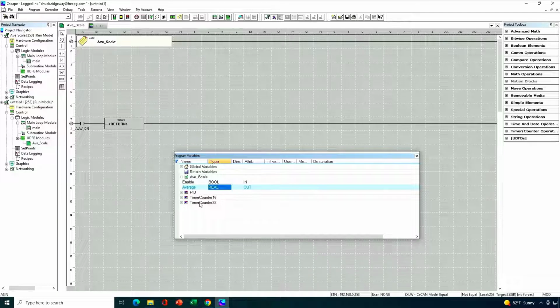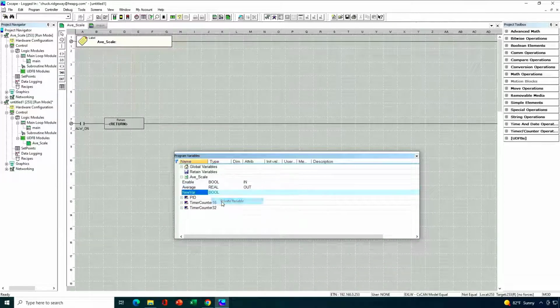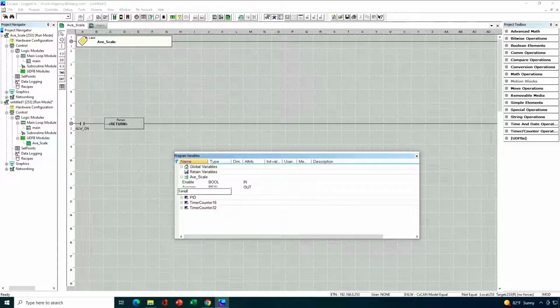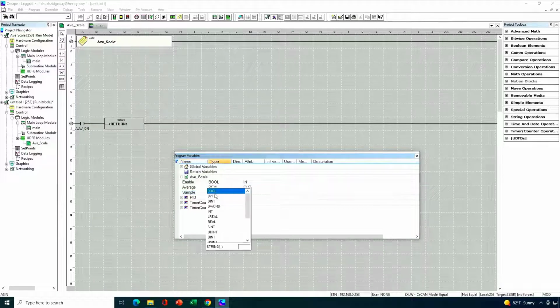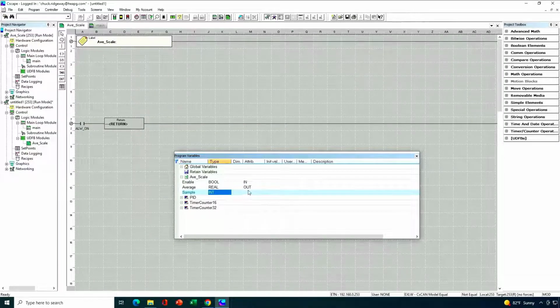And an internal private variable, just an example, was called sample, an integer-based array of 101 samples. The last member of the array, the 101st, we just used as the output for the shift register, so that's why I've sized it as 101 instead of 100. These are example input, output, and internal variables.